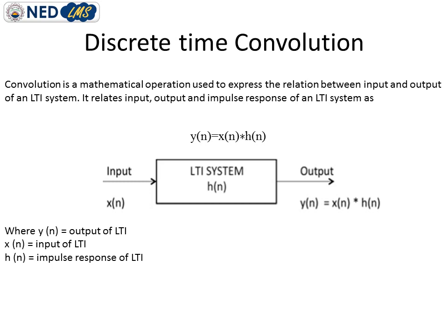In the field of signal processing, convolution is used to describe the relationship between three signals: the input signal, the impulse response, which is another signal, and the third one, the output signal. If you look at the block diagram, we have an LTI system, with input denoted by x of n and output denoted by y of n. Here convolution is used with linear systems.